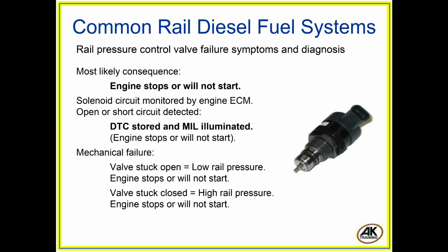Mechanical failure. Valve stuck open equals low rail pressure. Engine stops or will not start. Valve stuck closed equals high rail pressure. Engine stops or will not start.